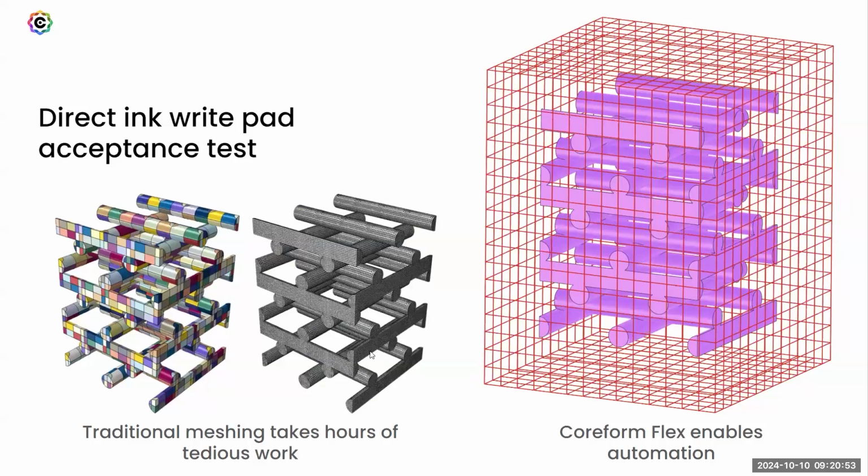And just to talk about some of the difficulties that this method has before we dive into the demo, traditionally, in order to build a body fit mesh, one would have to do a lot of partitioning, effectively almost building a hex mesh by hand through partitioning of the model in order to build this quality hex mesh for this problem. And this quality hex mesh is then required in order to be able to get convergence of the nonlinear solution in a reasonable amount of time while also getting accurate results.